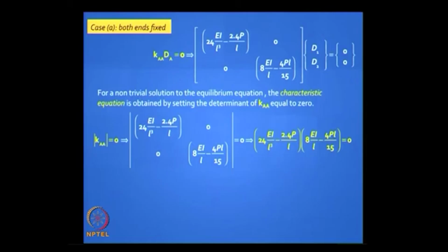It is a 2 by 2 matrix. So you have 2 solutions. What are those solutions called? They are called eigenvalues, and we are really interested in the lower of the 2 because buckling will take place at the lower load, right. So you can solve that equation and pick up the lower value, and you have got an answer,